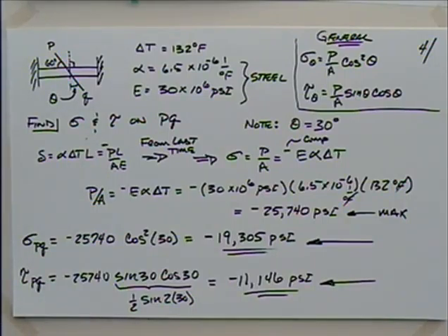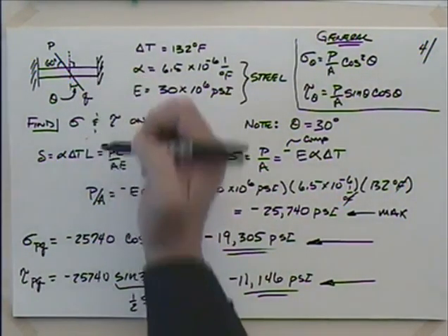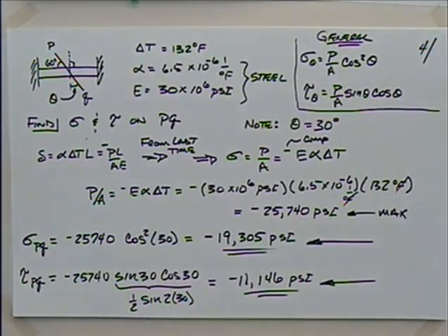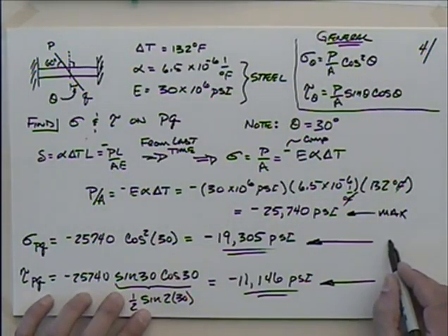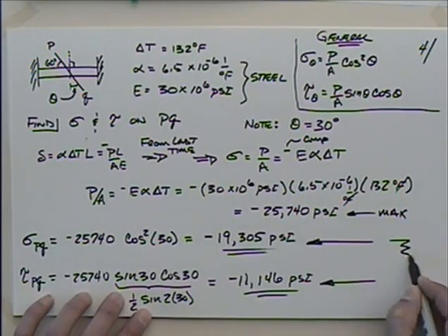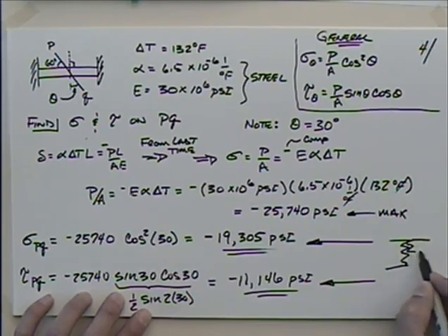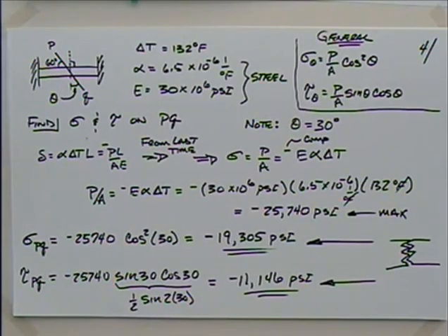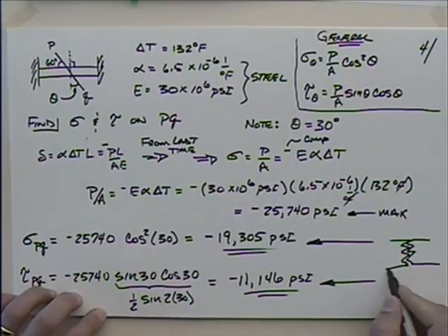I think you've got a homework problem that takes you through this. I think it has a solder joint or a glue joint that's at an angle. A lot of times they'll do that to get more surface area. Classic one is a finger joint. If you look at finger jointed wood, they cut it like this, right? You glue it together so you get more surface area. So you could talk about the stress on those inclined surfaces if you wanted to. There's a lot to be learned from gluing things together, glue joints, making models. You get some experience with some of that in the bridge design.